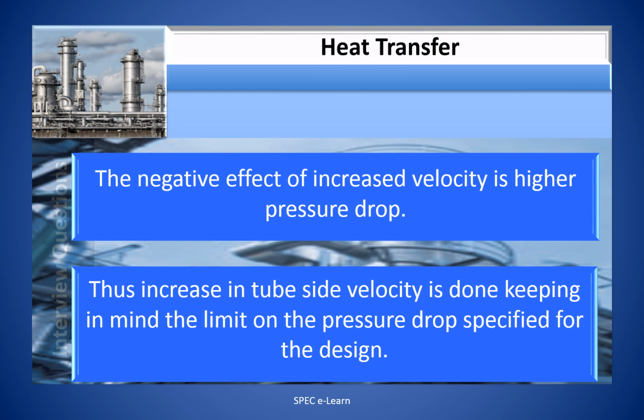The negative effect of increased velocity is higher pressure drop. Thus, increase in tube velocity is done keeping in mind the limit on the pressure drop specified for the design.